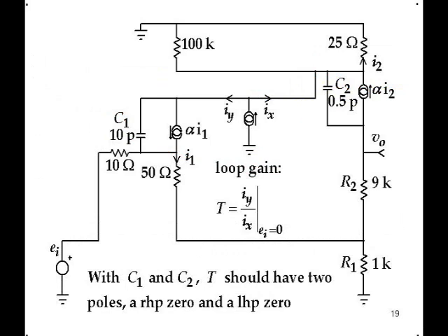And the reason for that is it's not an ideal injection point, because we've known for a long time that an ideal injection point is where you inject a shunt current at the output of a dependent current generator. And you can inject a series voltage at the output of an ideal dependent voltage generator. And there was only one of those two extremes available. But in the 1975 paper that I mentioned, I showed how to overcome that by doing a successive injection of a current and a voltage.